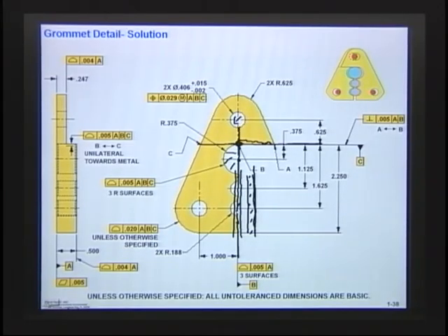But one way they could do it would be they have their origin. They could come down 2.250, and then they would touch spots. And as they touch spots, they're going to find out how much they're off that spot. And sometimes they do it like a whisker diagram, that if they touch a spot over here that's supposed to be 0, they find out, well, it came in at +5. Then they're going to check another spot, and they said, well, that one came in at -2, right? And then if I did that, I can come in as a designer, I can collect that data even from the coordinate measuring machine, input it, connect the dots, and actually draw you the picture of what the part is supposed to look like.